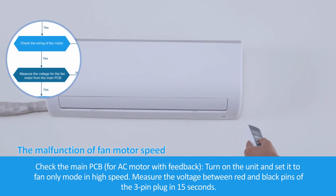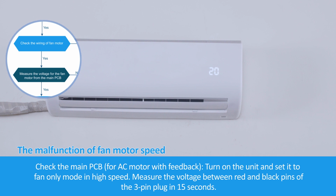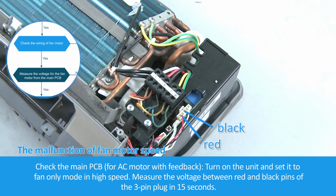Check the main PCB for AC motor with feedback. Turn on the unit and set it to the fan-only mode in high speed. Measure the voltage between red and black pins of the 3-pin plug in 15 seconds.